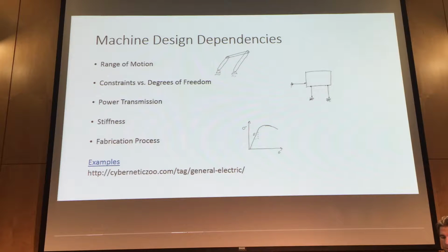The thing that happens is if you over-constrain a device, that means you have more than one mechanism holding it in place, and it becomes statically indeterminate. You don't know what the loading is inside each of those beams, and you can overload them. You're adding pre-stress, or self-stress, which takes the beams closer to their yield criteria before they're even taking any of the load you're expecting. And so that causes a lot of failures.